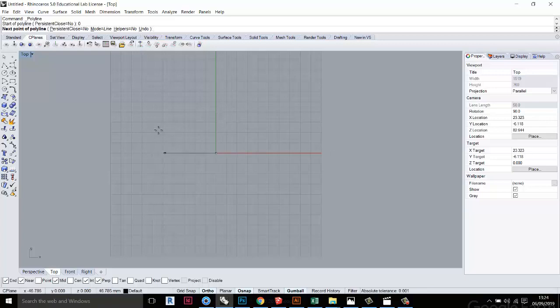Default is 90 degrees, but if you go into the settings you can make it any increment of degrees you like. So it's very useful for doing mirror lines where you want to ensure that it's a vertical or horizontal line that you're mirroring around. You can just turn it on all of the time and that will lock it to the orthogonal without having to hold shift, but I don't use it often enough to bother turning it on permanently, so I just hold shift when I need to.